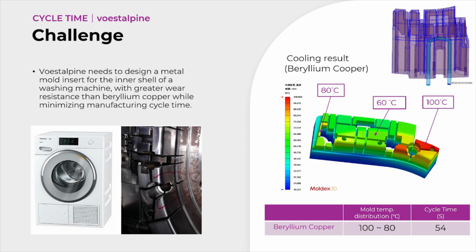It was originally thought that just a simple cooling channel routing through this insert was enough to extract the heat. Although, if we look at the temperature distribution from the simulation, we can see that the heat is accumulated in certain areas of the insert, causing a temperature variation across the surface of the geometry.